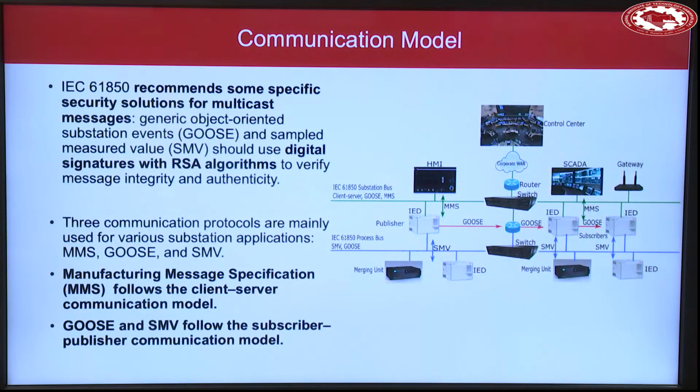Now, if I look at this, this is the typical scenario. In a substation, you've got different IEDs, the merging unit, different IEDs connecting to the HMI, router switches, this is the SCADA system, control center, and so on. Now, many of these devices operate with protocols at layer 2. In order to communicate with them, they don't need the internet because they are layer 2 devices. They can exchange data.